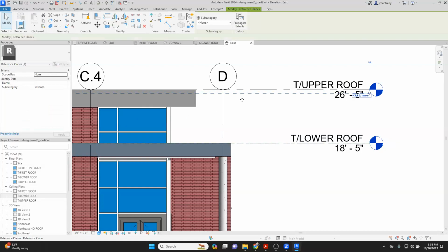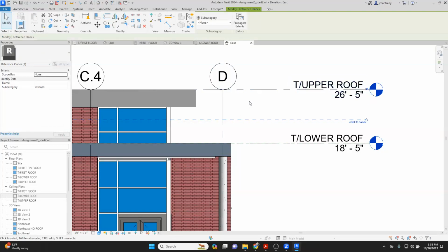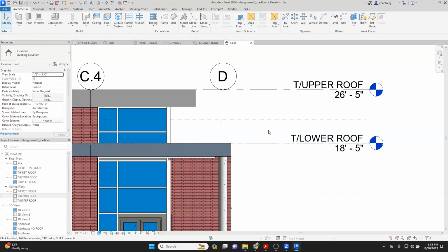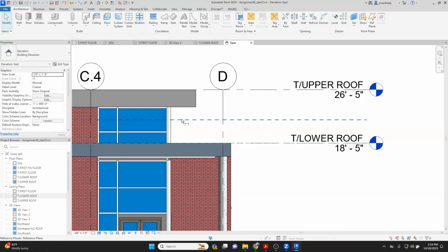This cut line needs to be somewhere like cutting through the windows here. If it was cutting through the windows here, then show what's happening between this line and the top of the upper roof. Show me that information on the floor plan as a reflection. But then I'm cutting through the windows. Anywhere. So if I do a distance here, this is 3'6". So cutting through the building at 3'6", cut plane, will guarantee it cuts through these windows. Anything above this floor, below that roof, anywhere will show me the reflected ceiling plan.